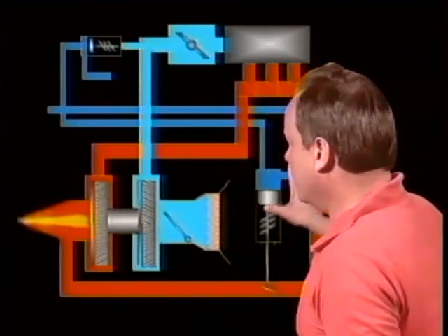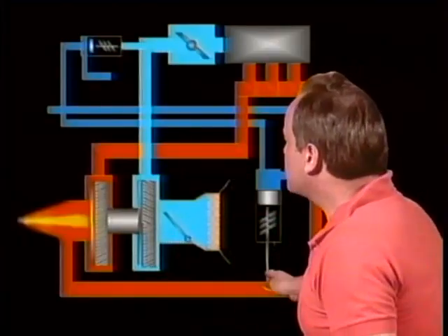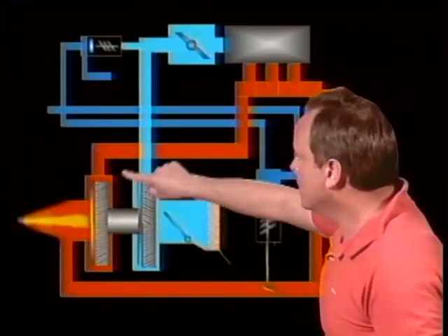All right, now here's what they're going to say also about this. If an engine is equipped with an external turbocharger, and the wastegate is closed, and you take off or start the engine with the wastegate closed, what's likely to happen? Well, if you have the wastegate closed, you've got the turbocharger running like the devil, and you could have serious damage to the engine because of an overboost, because you're directing all of the exhaust gases through the turbine. So if you start an engine with the wastegate closed, you could forget that you have it closed, and you could overboost the engine. And that's one of the dangers they're talking about.